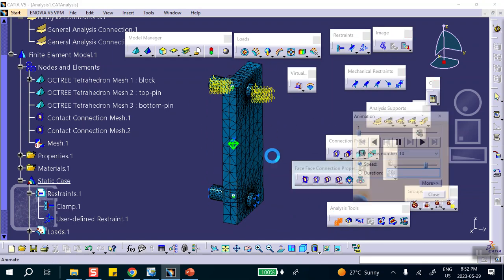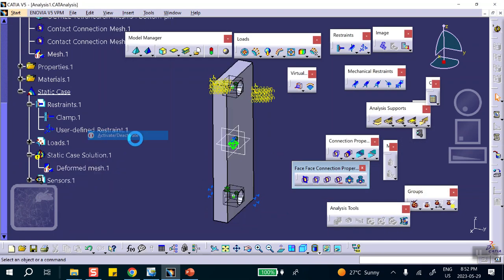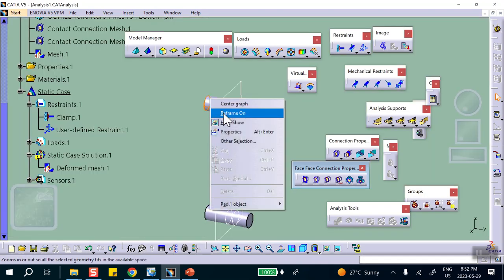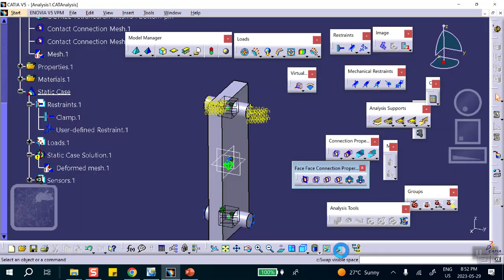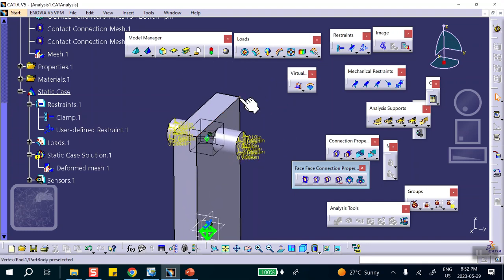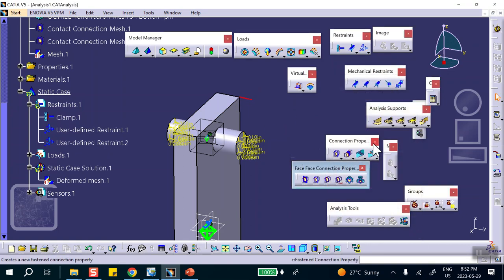So we stop this, and now we're going to deactivate this plot and prevent that rigid body motion. By the way, these pins are still here. Even if they're not showing, they were just in hiding. You can see that. So I'm going to take one corner point and say, you cannot move in the direction Y. So, user defined constraint: this corner point cannot move in the direction Y. That will take away the rigid body motion.